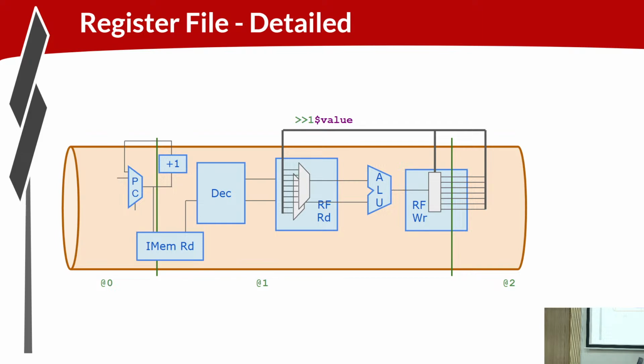If this instruction is doing a read, it's the data as updated by this instruction that we should be reading. So when we put all of this in the context of a pipeline, as it would be utilized by the CPU, we want the data that's written to be in stage 2 for the read in stage 1.